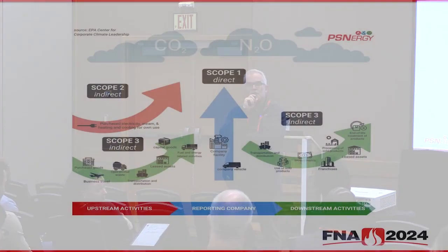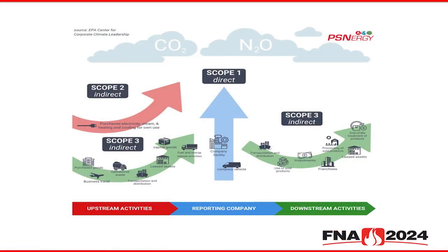Well, our VP, how do you view this taking place? The heat applied to the metal on open fire is very dependent on the shape of the flame and the luminosity of the flame. So there is a little bit of adjusting. Oh, I'll get the flame where I want it, or I need it a little bit longer. But our VP of service would tell you that you get yourself in a lot of trouble when you're adjusting ratios by sight, sound, or whatever, because you can actually get into an explosive situation on one end or the other.